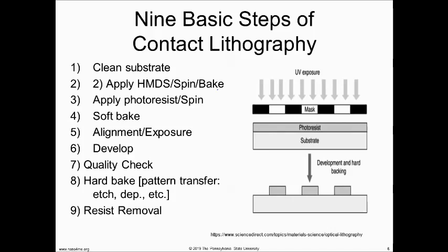We could also remove the photoresist with, literally, nail polish remover, acetone, the stuff you buy in Walmart or CVS, and that's how you'd remove that organic polymer, like the paint or a nail polish, right? And we could use acetone and IPA and DI water to remove photoresist. But once we do a process like etching, we usually burn it on, so it's really difficult to get rid of. So the wet chemistry method is not preferred. Actually, the oxygen plasma is probably a better, more concise way of cleaning up that photoresist from the wafer. So does everybody understand that?